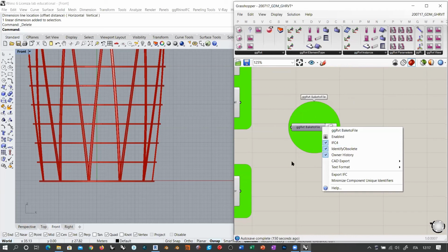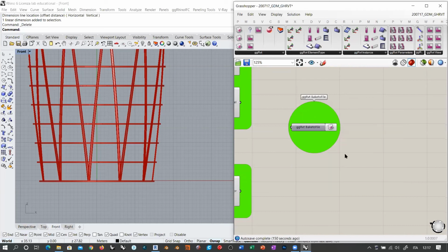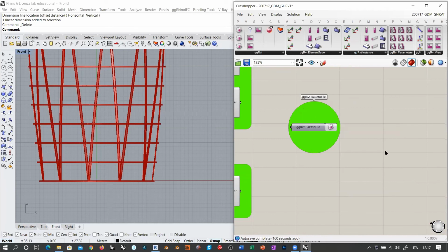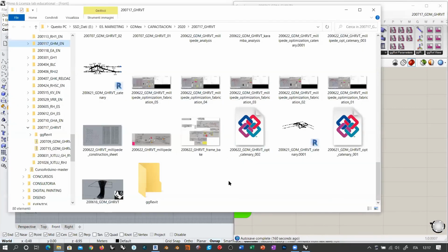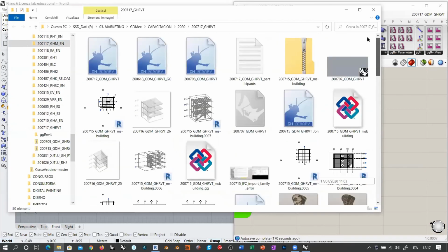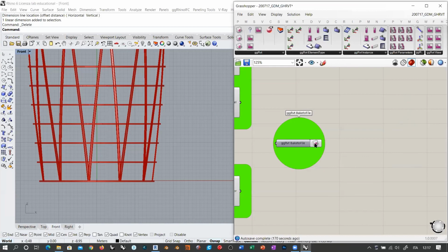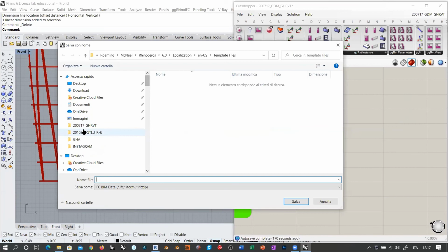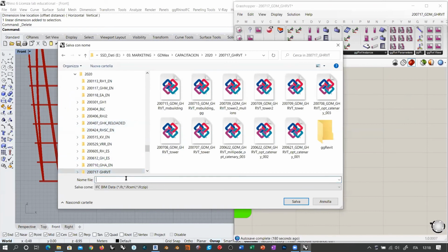If you also want a separate CAD representation, you can also select these SAT or DWG if you want to use this for other purposes. But the important thing is to create the IFC file. Okay. Here's my folder for this course. So let's double click here. The browser pops up. I'm going into our folder, and I'm going to name this